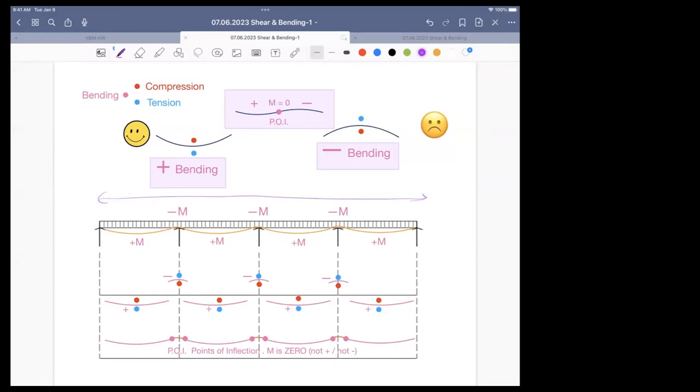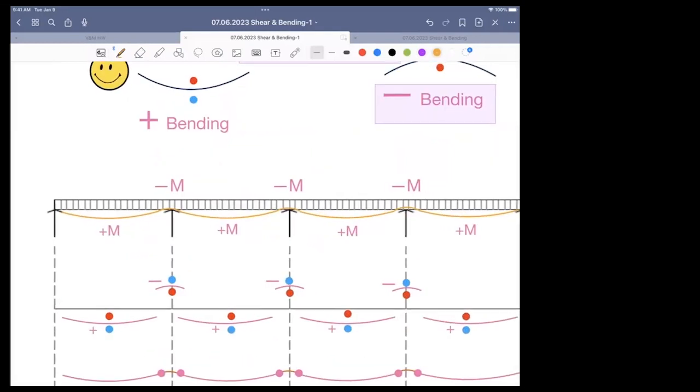I have no interest. I can tell you one thing: the maximum shear is going to happen at the support, and the maximum moment is going to happen somewhere in the middle. I can tell you as much. But I am much more interested in this problem of looking at the deflected shape, because it answers everything and their brother. The deflected shape looks like that. That's what a continuous beam would do.